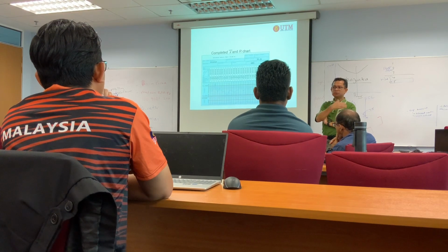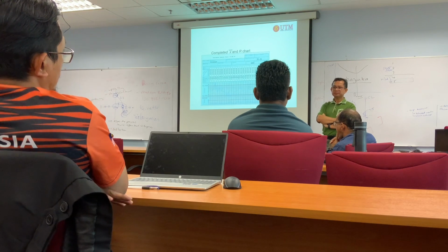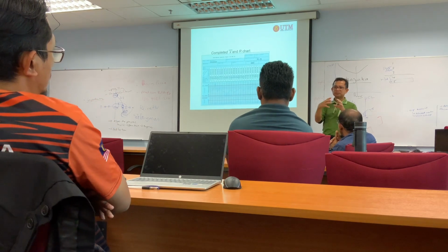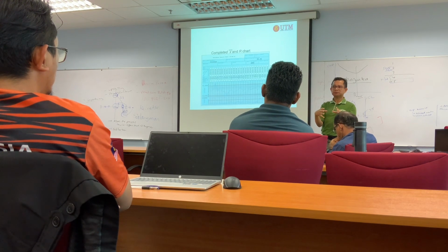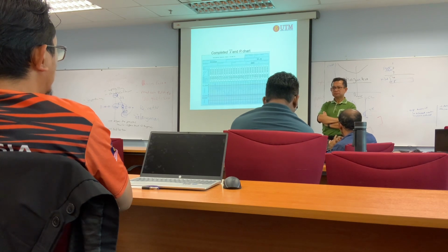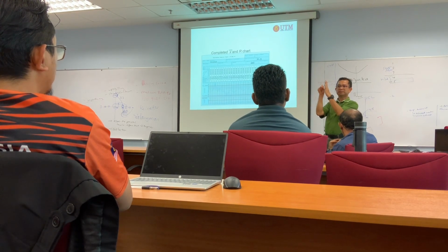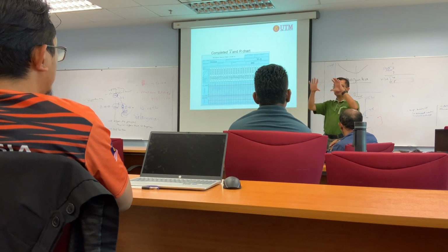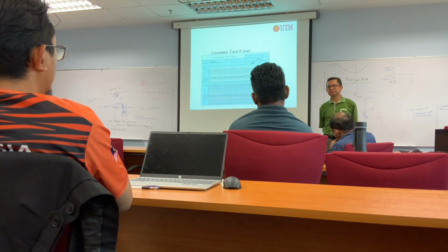But if you want to show it to a third party, because that is not a standard approach, better you have SPC. Because we want to say how accurate the result is that we get. You show how accurate, but that is based on one sample. But we want to see the trend of your entire week or entire month of production.